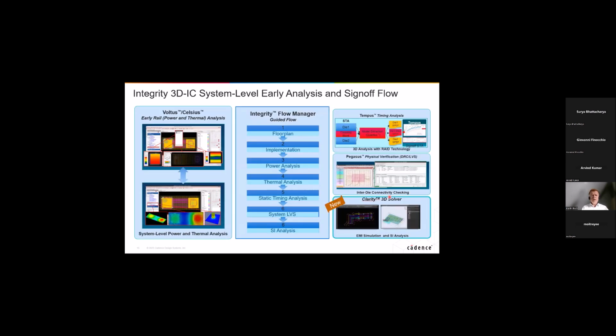And the beauty of this Integrity 3D cockpit or planner is that we provide also a kind of flow manager, so you don't need to import, export data between the different tools. The database is kept in this multi-technology environment, and the flow planner would guide you through the steps of designing this system by creating floor plan, doing the individual implementation task of the different dies, doing power integrity, thermal integrity, static timing, system LVS.